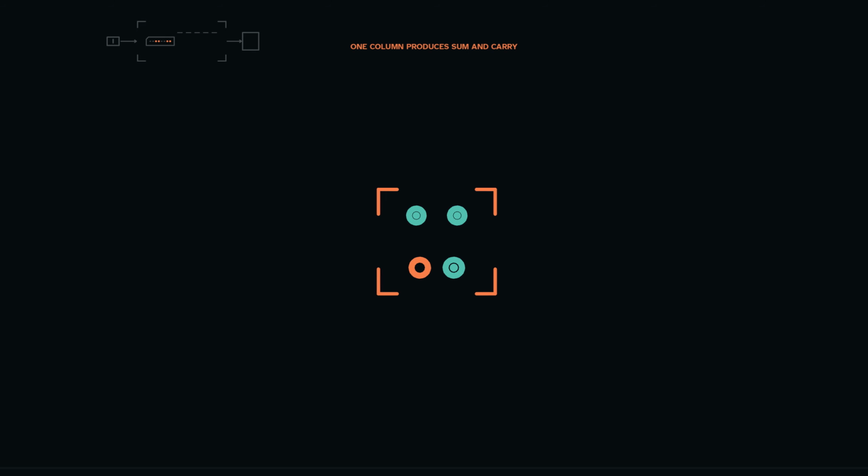The sum output matches exclusive OR, because it is 1 when the inputs differ. The carry output matches AND, because it is 1 only when both inputs are 1. This pair of certified logic relations is a half adder. Its limitation is in the name. It cannot include a carry arriving from a lower position.